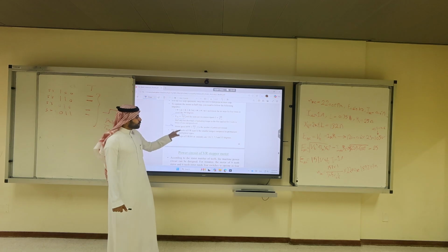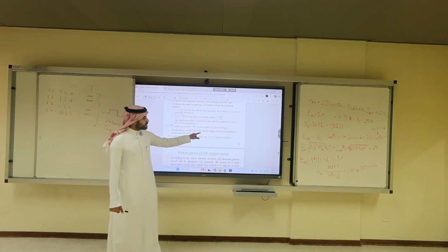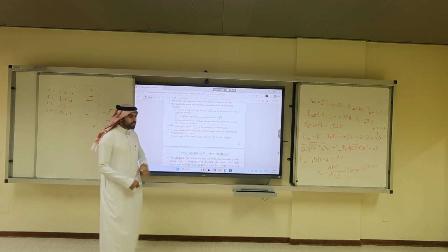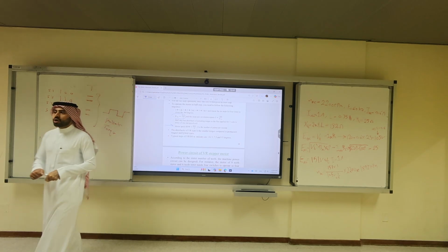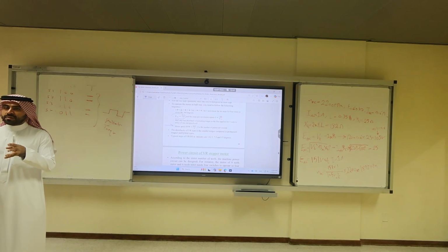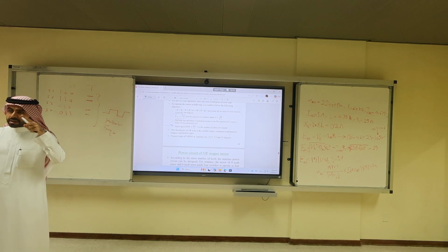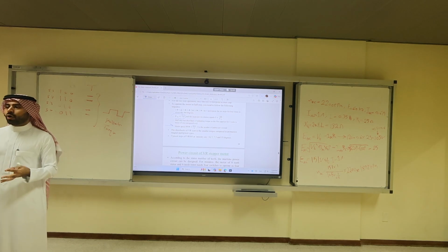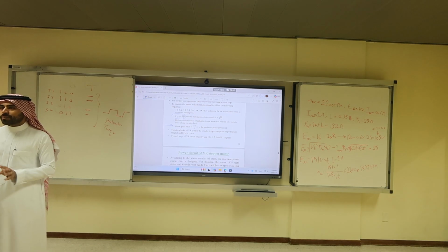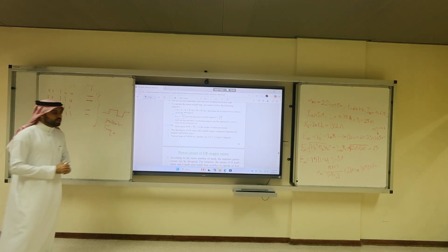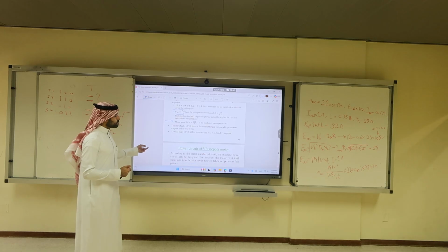The drawback of the variable reluctance motor is smaller torque compared to permanent magnet or hybrid. If you have a permanent magnet, you get flux from the magnet and flux from the coils. If you don't have a permanent magnet, all of your flux is from the coils. Does it make sense? So a permanent magnet acts like a booster for the flux.